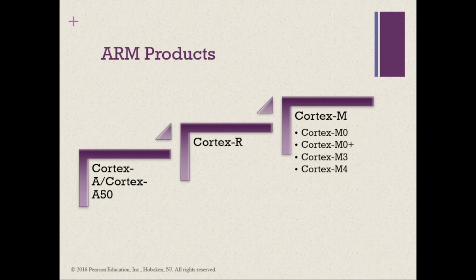There are currently four versions of the Cortex-M series, starting with the Cortex-M0. This is designed for 8 and 16-bit applications. This model emphasizes low cost, ultra low power, and simplicity. It is optimized for small silicon die size, starting from 12,000 gates, and used in lowest cost chips. Next, we have the Cortex-M0 Plus, an enhanced version of the M0 that is more energy efficient.